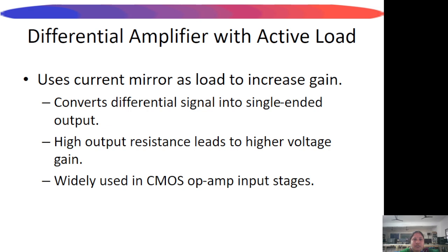This configuration improves the isolation between input and output. However, voltage swing is reduced. More headroom is required for proper operation. Cascode amplifiers are used in high gain applications. They are common in analog IC blocks. Designers must consider trade-offs carefully.